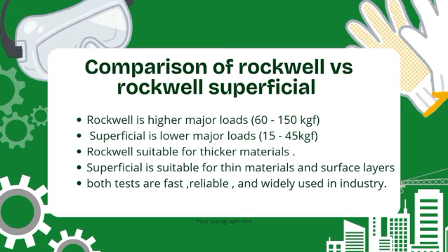And the next one is application of the Rockwell test. Heat treated steels and alloy testing, quality control in automotive and aerospace industries, testing of shafts and machine components. Superficial test is used on thin sheets and plated materials, and inspection of surface hardness after heat treatment.